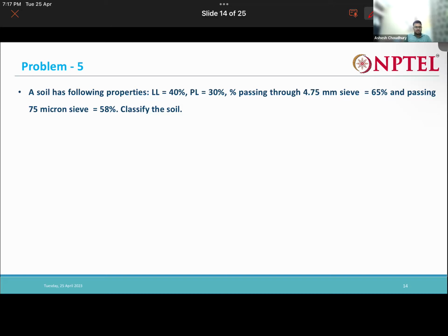We had studied all those things. We studied the various percentages between which one classification applies, and above or below which another applies. So 5 to 12%, I guess: below 5% it will be only gravel, a coarse classification, above 12% it will be the other. Many things like that were there, and we studied all of those.